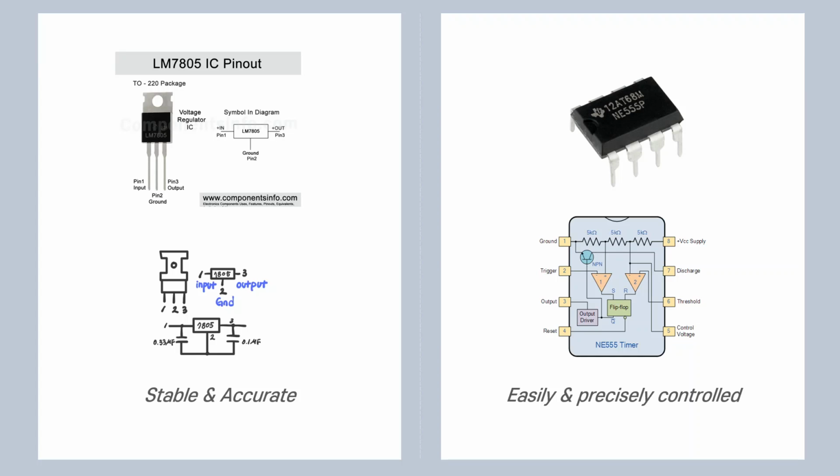The NE555 element has the advantage of being able to be controlled simply and accurately. When operating in the time delay mode, the delay time interval can be precisely controlled through externally connected resistors and capacitors.